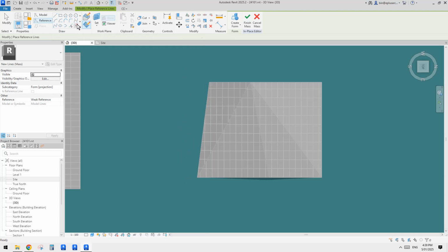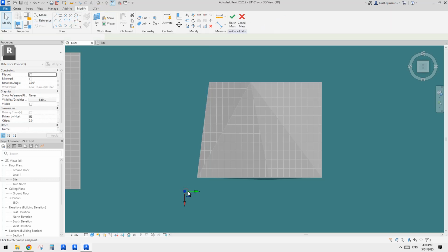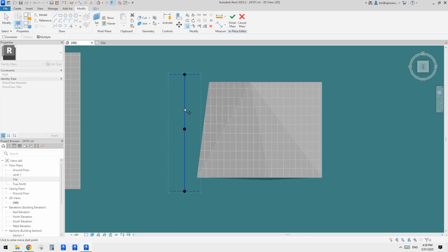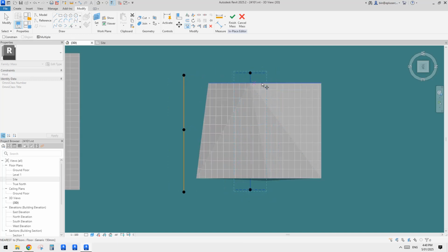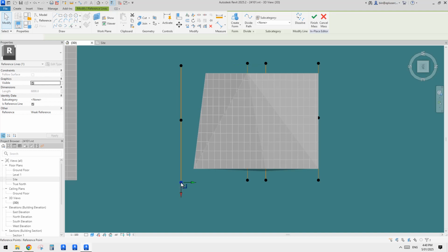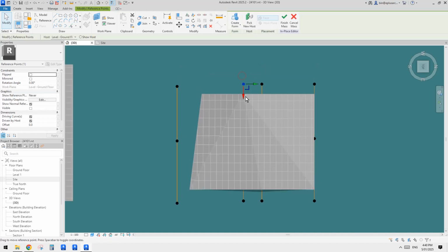Yeah, it looks like we need to make it straight. So maybe I'll just use point instead of lines. Because with points, we can just copy them. So and then use spline through point, make a reference line, and copy this one. So maybe I'll just copy this one to roughly align with that point, and maybe just do another one roughly align with this, and then this. Okay, so here I'm not sure, it looks like it's not aligned, but actually I'm going to just intentionally make it not, you know, aligned.